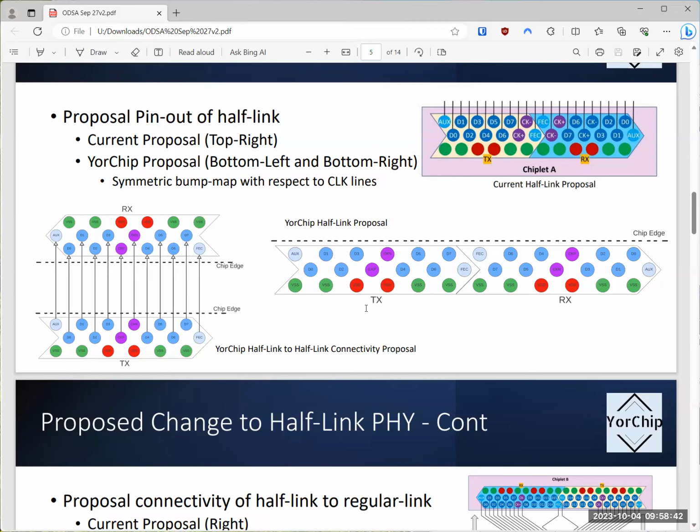Not necessarily. At least in our use case, we expect to have a certain number of these because our host chip is connecting to many device chips, as an example. So this is a specific use case for when you have a processing chip that has a lot of... Understood, but that's actually okay, in the sense that you were going to need scribe lines and separation between the device chips anyways.